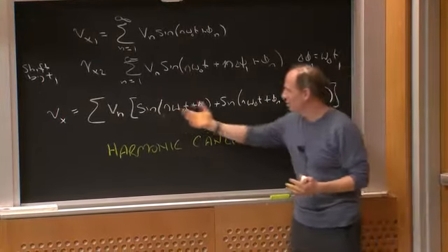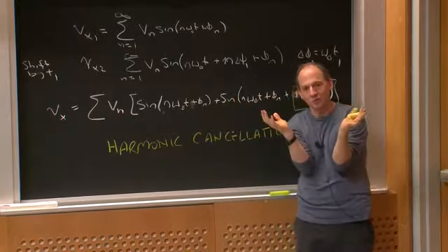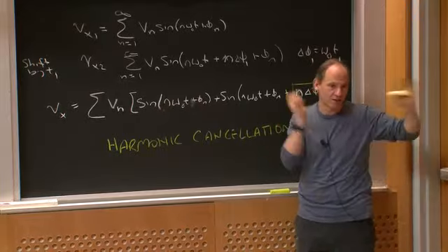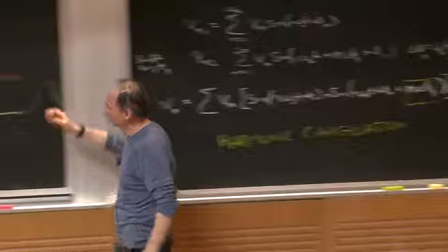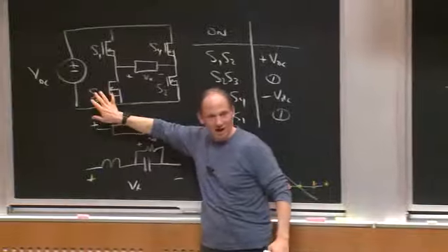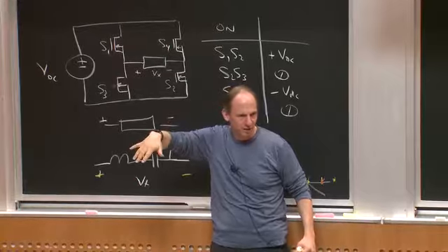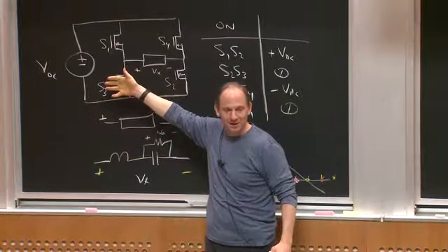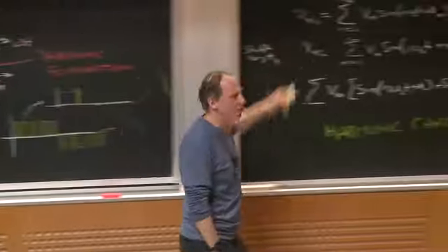In other words, if I take 2 half-size waveforms and add them up, the most I'm going to get is back to the original. Other than that, I'm just going to get some degree of cancellation. So I don't introduce new frequencies by doing this trick. I just kill frequencies. So yes, my original waveform, because of the harmonic cancellation of the 2 half bridges, has no triple-N harmonics, no 3, 6, 9, 12, 15, 18, and so forth, right? I don't have any evens because of the half-wave symmetry. And then if I do this trick, I kill off all the 5N harmonics.